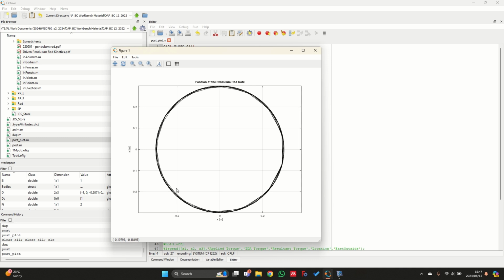The reason for this is simply due to the reporting time step that you're using. If something like this is bothering you or giving you inaccurate results, then you will probably have to decrease the reporting time step. This will, of course, cause the system to run a bit longer, but you will get better results.